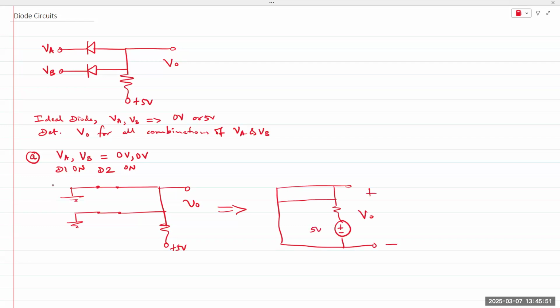So what is V out? Look at the top terminal of V out. It's going towards the left, coming down, going towards the right. It's all one single node, the exact same node, so you're measuring voltage at the exact same node. Therefore, V out is equal to 0 volts. If you look at the drawing on the left, you can see V out is directly connected to ground, so you're measuring ground, or the reference point. So V out is equal to 0.